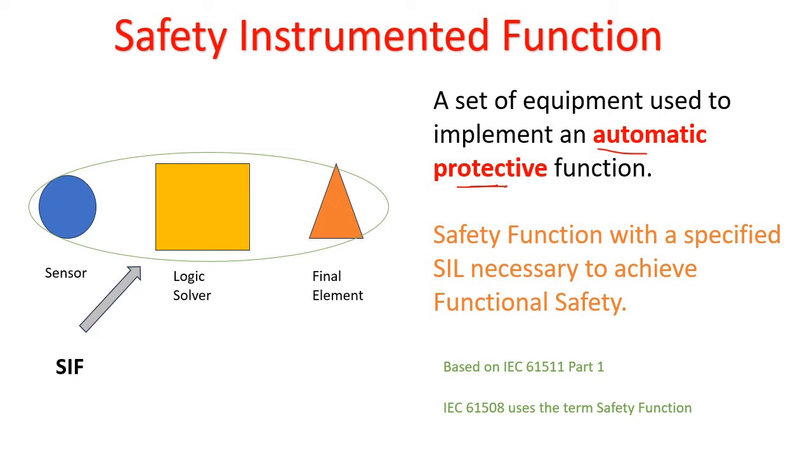Now there is another standard, the umbrella standard for functional safety, that is known as IEC 61508. In IEC 61508, there is nothing called safety instrumented function. The same thing, the safety instrumented function, is called safety function in that standard. So just remember, as per IEC 61508, safety instrumented function is synonymous to safety function.